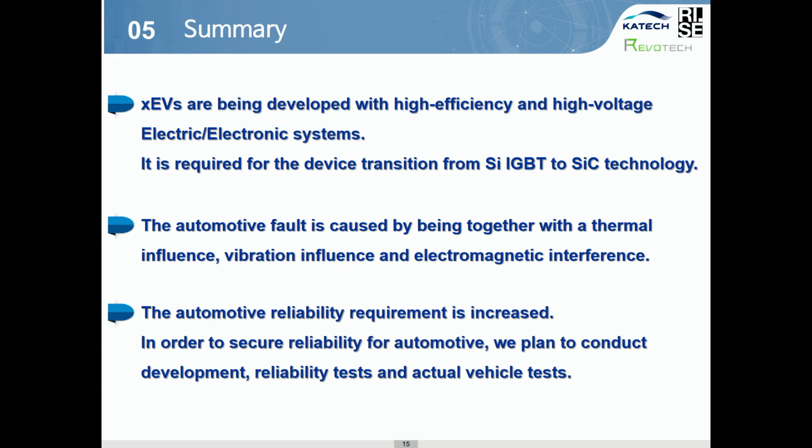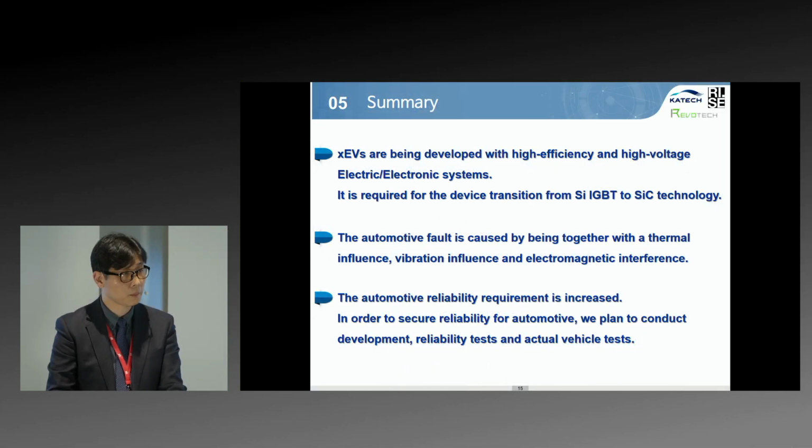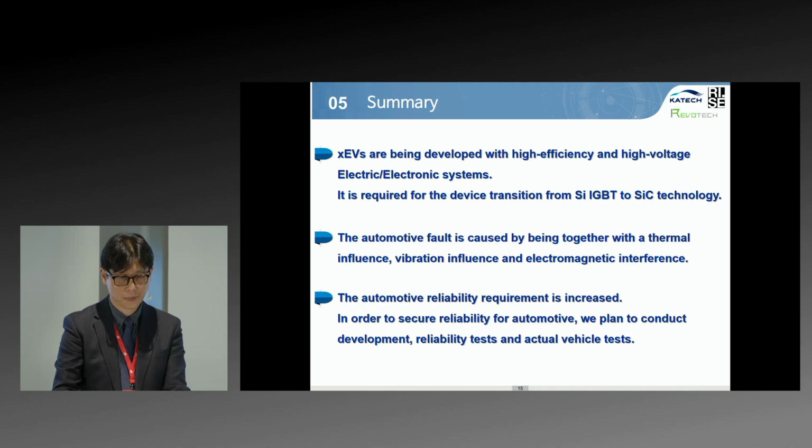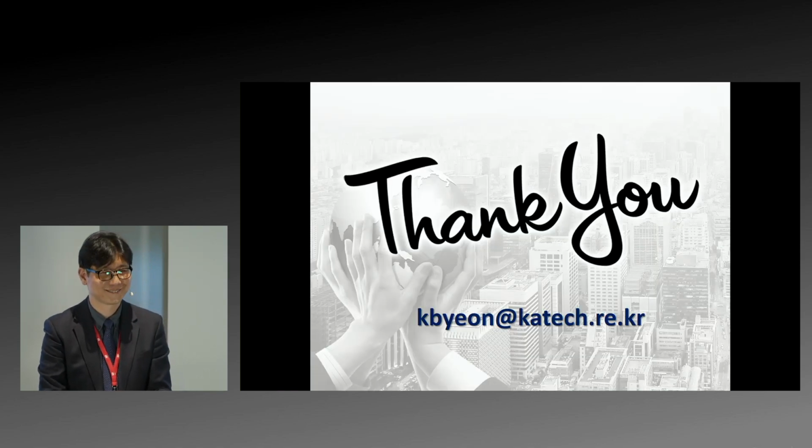Summary. xEVs are being developed with high efficiency and high voltage electronic systems. It requires the device transition from silicon IGBT to silicon carbide technology. Automotive faults are caused by the combined thermal influence, vibration influence, and electromagnetic interference. The automotive reliability requirement is increased. In order to secure reliability for automotive, we plan to conduct development, reliability tests, and actual vehicle tests. Thank you for your attention.